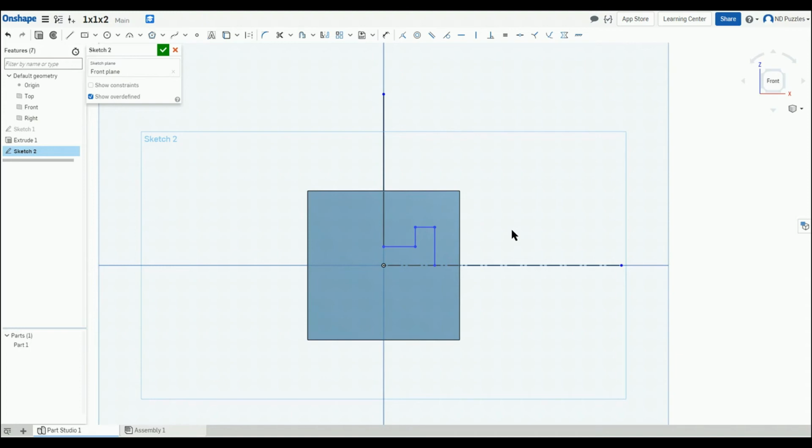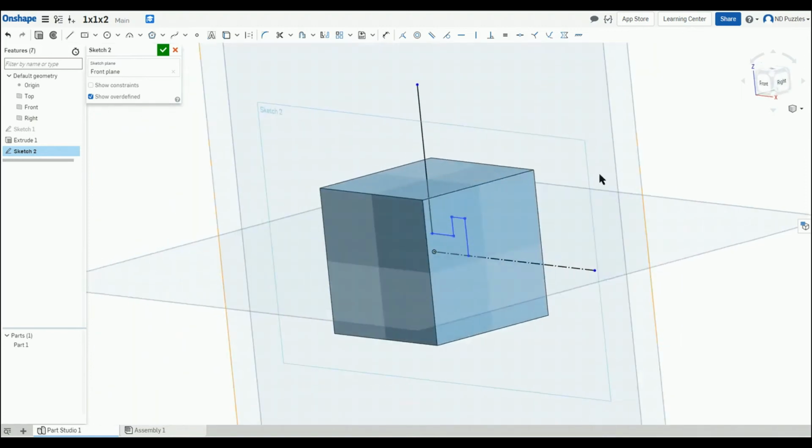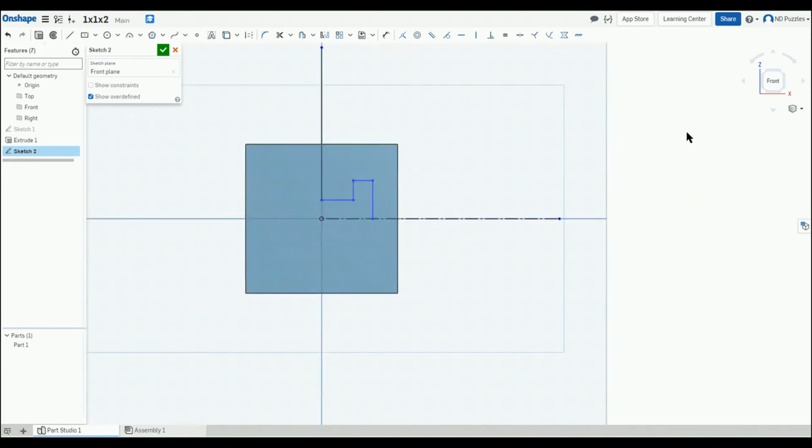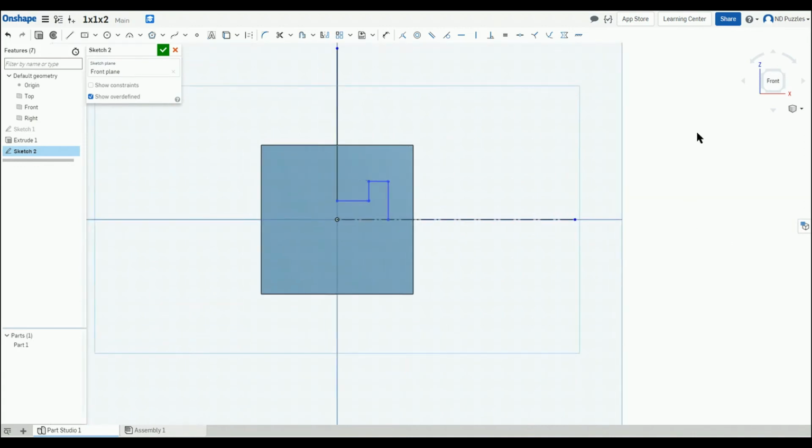Click on the line tool, and you will be able to draw a line. If you want to be professional, also click at this dotted line thing up there to make the line look different than our others. That also prevents the program from confusing it as part of your sketch. Fetch the origin and draw the line to the right.